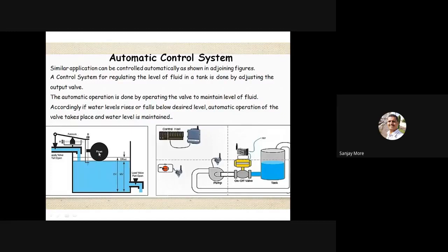If the water level reaches this point, the float will go in an upward direction, and the fulcrum pin connected to the shut-off valve moves to a downward position, and the water supply will be stopped after the tank is filled.